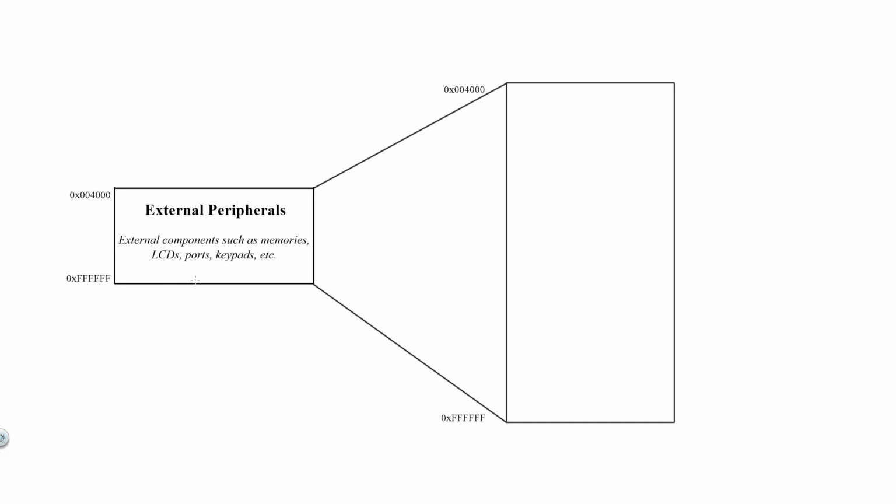So the difficult part of EBI to understand for a lot of students is the idea that we are simultaneously enabling and accessing external devices using load and store instructions instead of manually selecting external devices via software-controlled signals, similar to the way we did it in the previous solution. This may be hard to grasp at first, but remember it's the reason EBI is so useful.